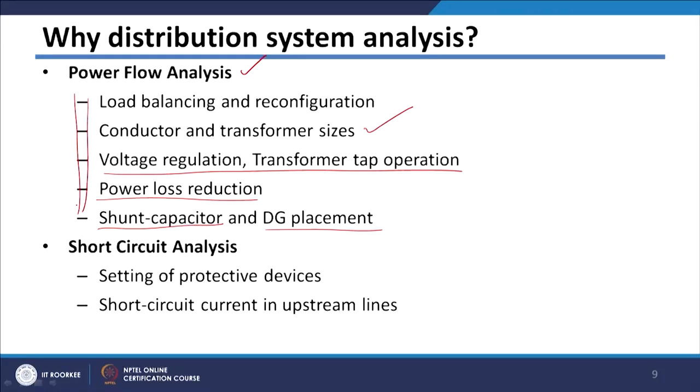Then short circuit analysis is required while doing the settings for protective relays or during the relay coordination in a distribution system. Also to calculate short circuit current in the upstream network. So, we need actually results from short circuit analysis during these design stages.